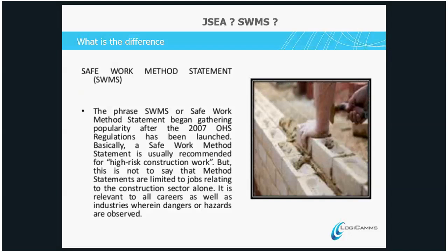So what is a SWMS? The term SWMS gained common usage in Victoria following the introduction of the OHS regulation in 2007. A safe work method statement, or SWMS as its acronym, is prescribed for all high-risk construction work. When it first came out, it was targeting only the construction industry, and it was specific for high-risk construction work. That does not mean that its use is limited to the construction sector. As we now know, it is common across all industries.